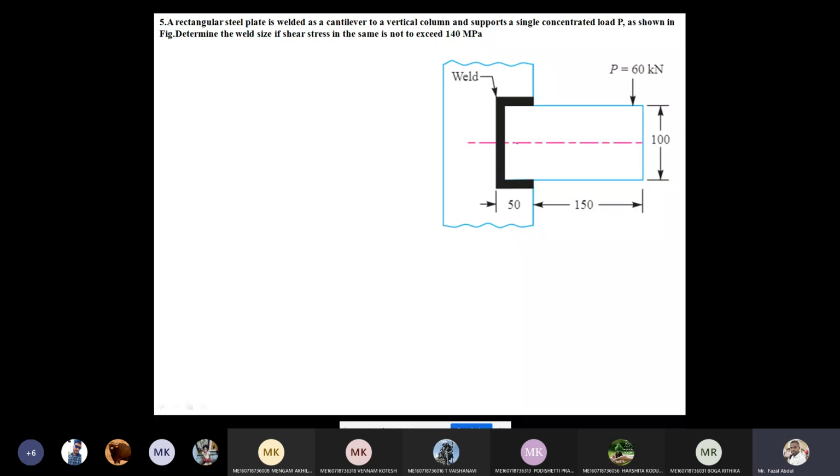CG is going to lie here for this figure. Now from here to here, the distance is known as x. This x value is given in the table. This equation you have to remember, Babu. L square by 2L plus b. Okay. Now what is L?